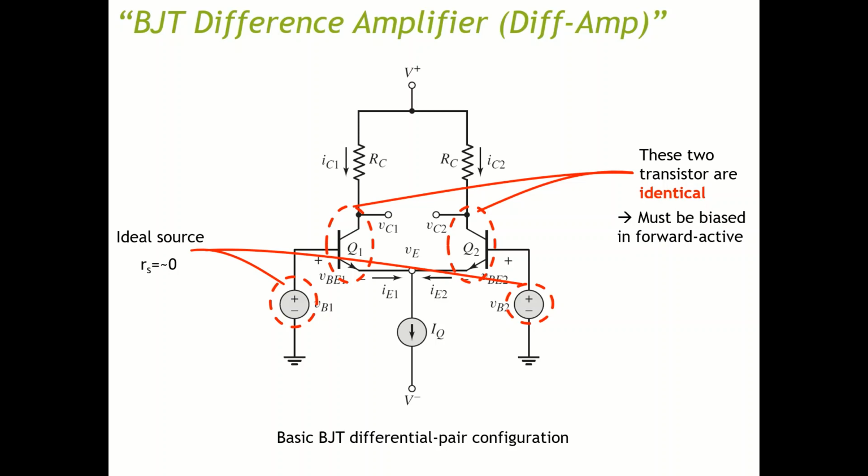The circuit is then referred to as a DC coupled differential amplifier, so differences in DC input voltage can be amplified. Although the difference amplifier contains two transistors, it is considered a single stage amplifier, so not multi-stage. The analysis will be shown later as we go through.